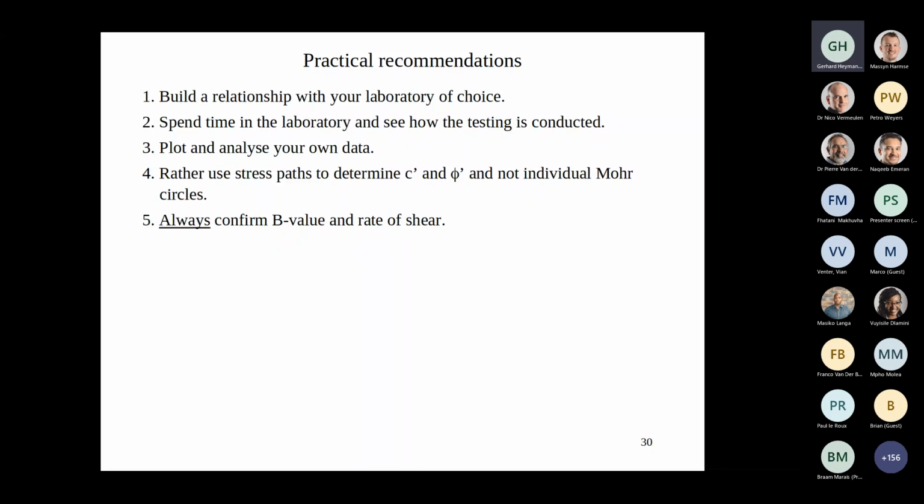And then point 3, I've said many times today, is plot your own data and analyze it. Do not rely on the lab to do it, not because they'll do it wrong, but because it'll give you much better insight into the behavior of your material. And you are the design engineer, and quantifying the design parameters is your responsibility, not the lab's.